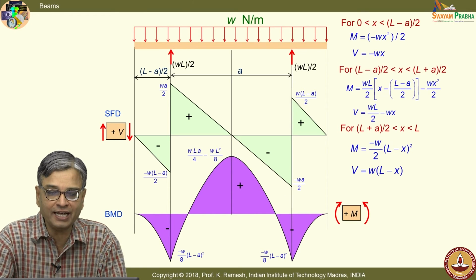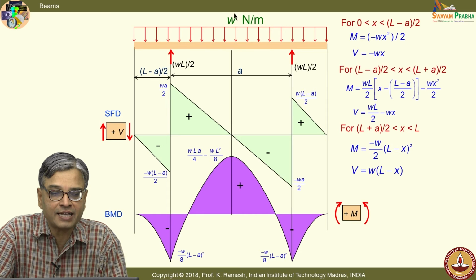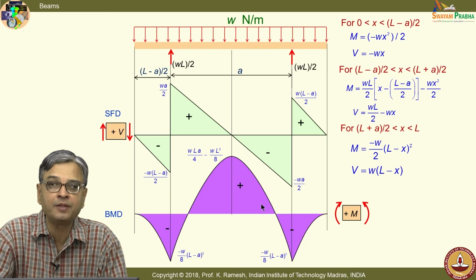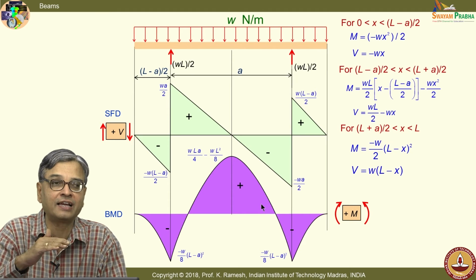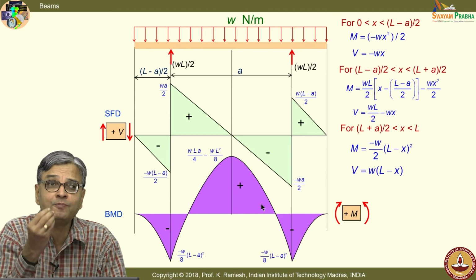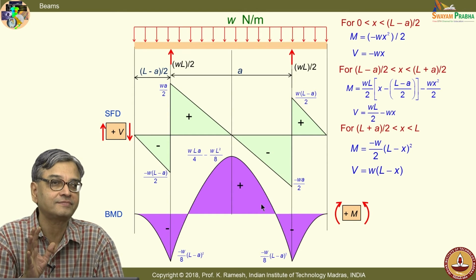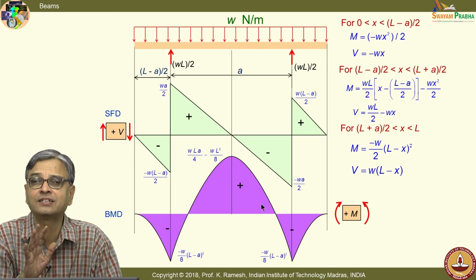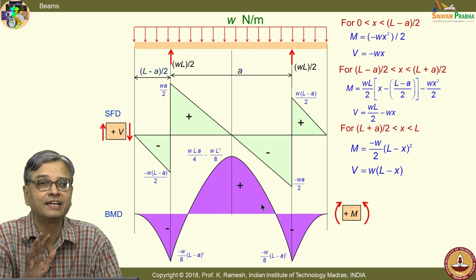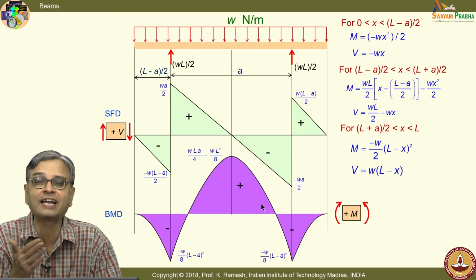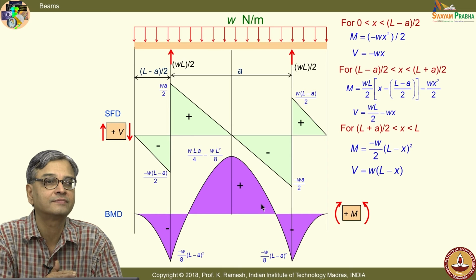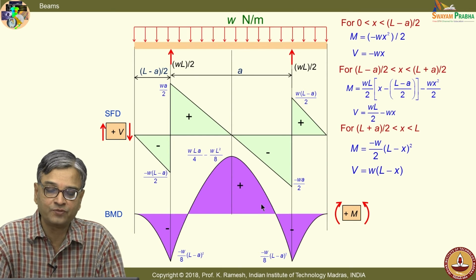So, now do you realize when I say that you have to plot the loading diagram, shear force diagram and bending moment diagram one below the other, it at least prompts you to think and find out whether your answer is correct, whether you have drawn these variations correctly, translated your expression correctly in the drawing. So, that is very, very important.